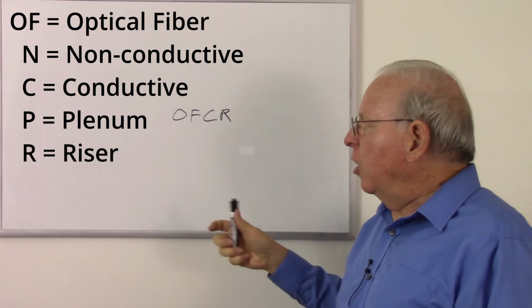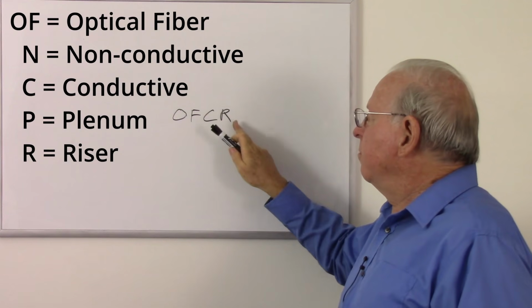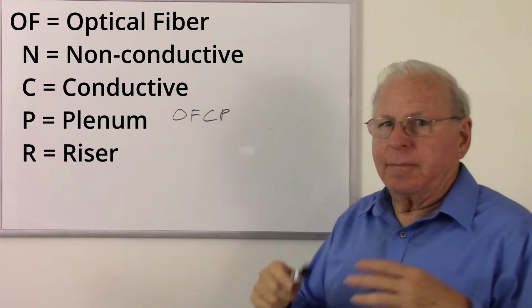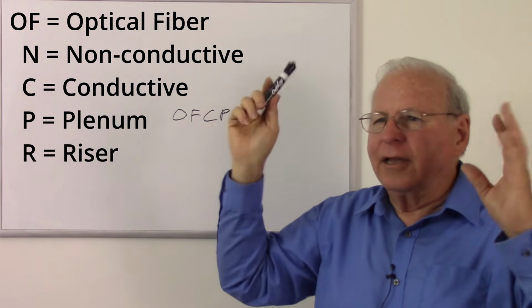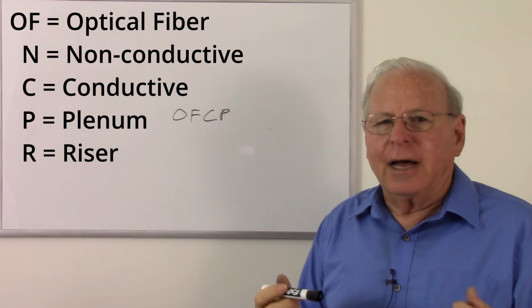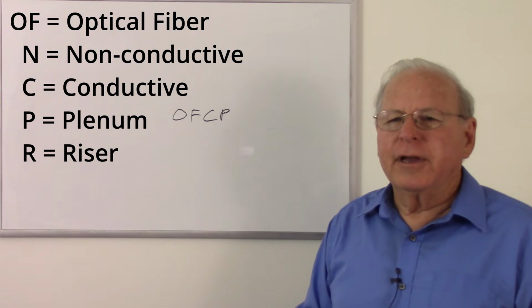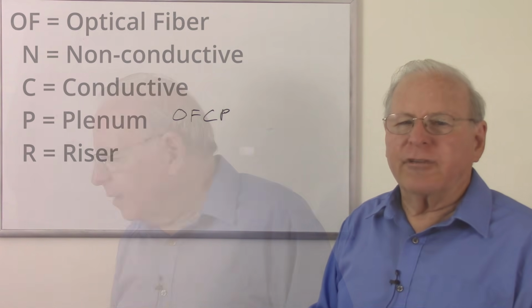And you can use it out in the open. But if you want to be sure you're installing anywhere you want to, make sure you use plenum cable, because that can be installed vertically, horizontally, in air handling areas, wherever you want to, where riser cable cannot be installed everywhere. So plenum cable is more expensive, but it's more versatile than riser cable.